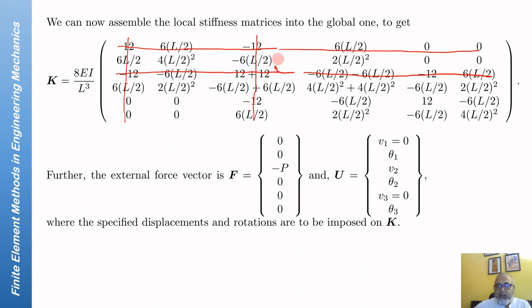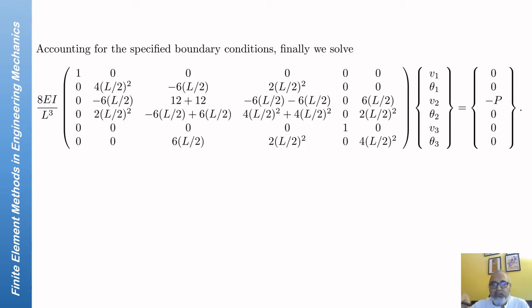Replace the diagonal entries by 1, so that the first and the corresponding equations become identities, and I get the modified K matrix, which we had earlier called K prime, the K prime matrix with the information about the boundary conditions built into it.